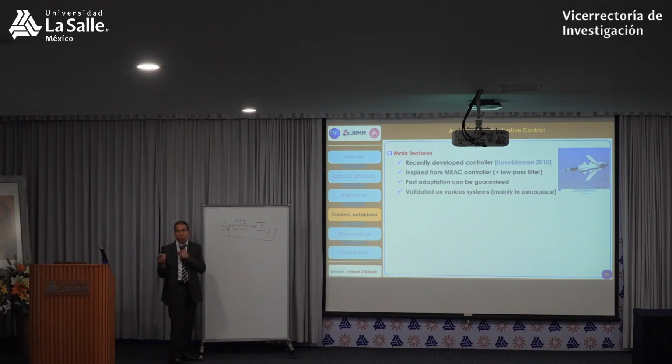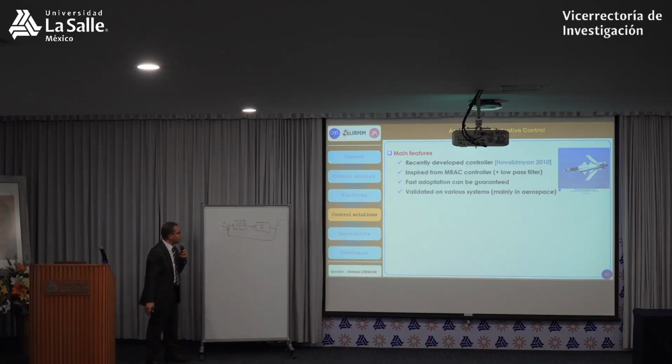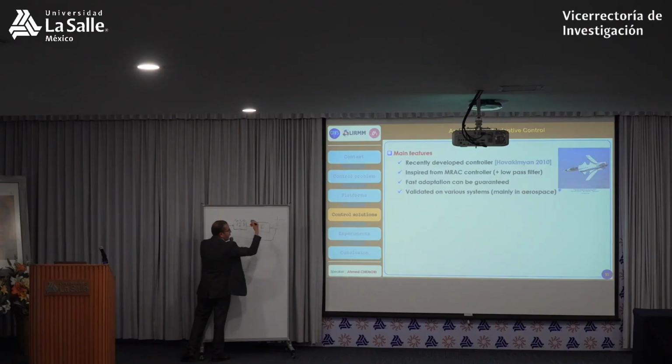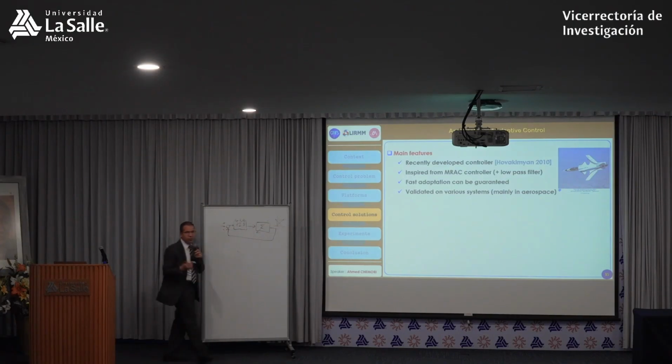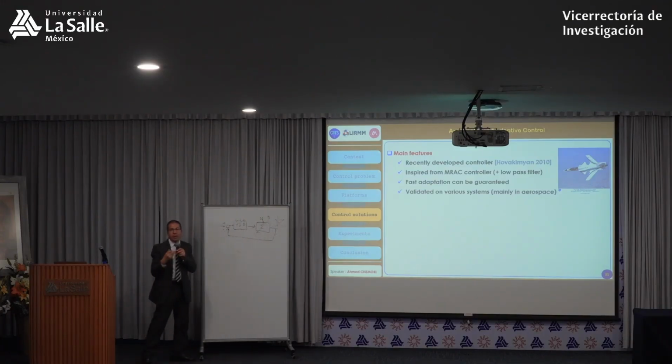And you design your control based on the desired performance. It means for your closed loop, you fix the performance: I want to get this overshoot, this settling time, and so on and so on. Once you design your controller based on this system, you tune those gains to obtain this performance. However, if something changes here, the performance may be lost. You introduce a big uncertainty or disturbance, so this may change the performance, and you will lose the performance.